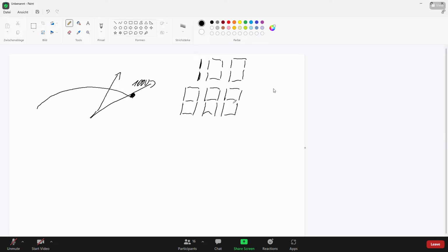And therefore, it is very important to know at which point is the end of the range. Because when the device is showing 120, it can also be 130 or 110, because outside of the end of the range the given error is not valid anymore. The given error is only valid until the end of the range.